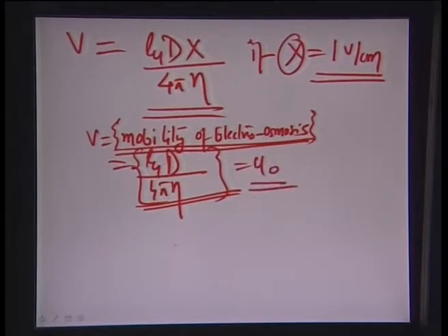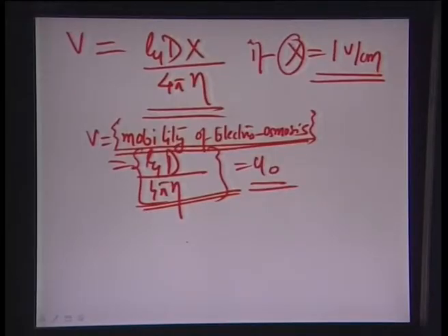Okay. And we can further do some analysis, because when we talk about microflows and capillaries associated with these kinds of flows, we need parameters like the flow rate. And velocity essentially is nothing but the flow rate per unit area, as we all know from our fluidics background, right. So volume flow rate Q divided by some area would represent the velocity.